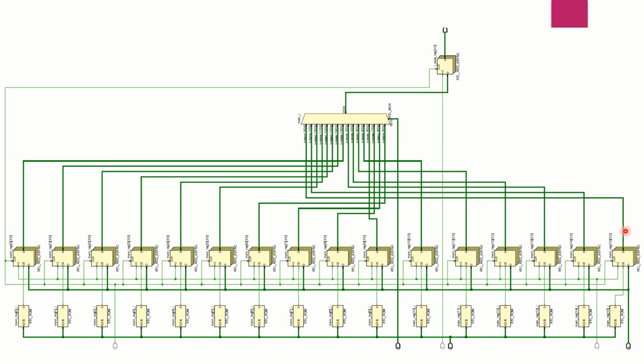As for the read side, when the positive edge of the read clock occurs, depending upon the read address pointer, the mux will take the data from the appropriate flops and transfer it to the output flop, which will then give out the read data. The reset signal goes to all the flops, including the write data flops and the read data flop, and resets them when the signal goes low.